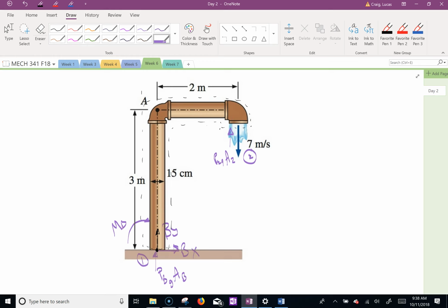Okay, it's a fire hydrant with stuff sticking out horizontal on one side and it's shooting out at an angle on the other side. So they want you to figure out the moment at B and find the reaction forces. So always remember, we also have weight, right? A weight force. I think the homework neglected it. So you have body forces, which is weight. You have surface forces, which are pressure. And then you have reaction forces. That's all the time when you have this stuff.